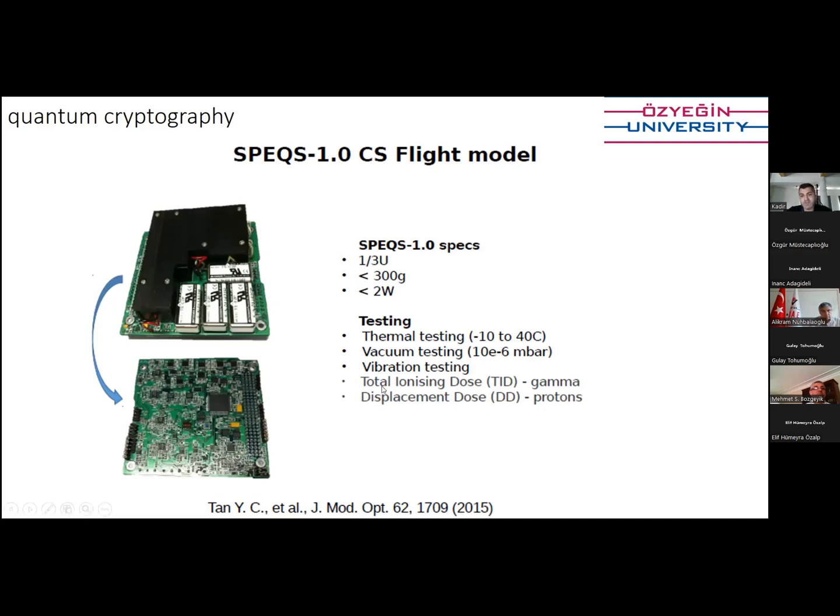And then there are radiations from the sun, gamma and proton radiations, which are available, unfortunately, in low Earth orbit. You need to do dose testing first, to see if the electronics here, the chips, and even the crystals and avalanche photodiodes, everything is intact when there is this kind of radiation. Of course the radiation will kill them eventually, but we wanted to see roughly how long it would take. We don't want the whole payload to die in 6 months. Therefore you need to make some shields.